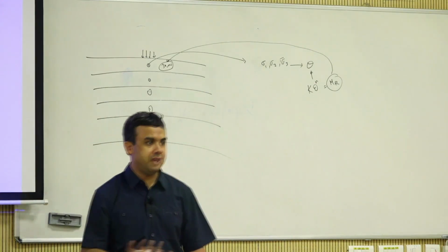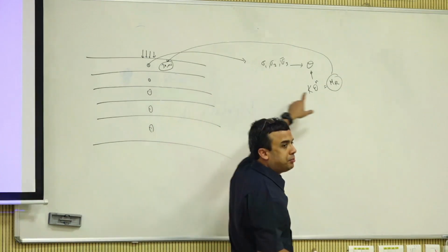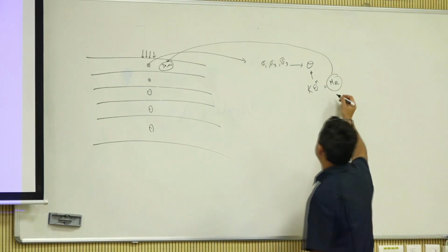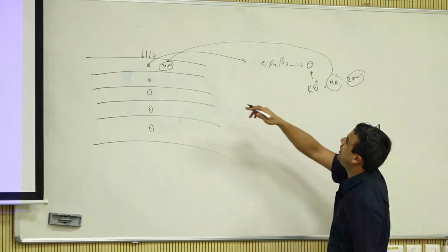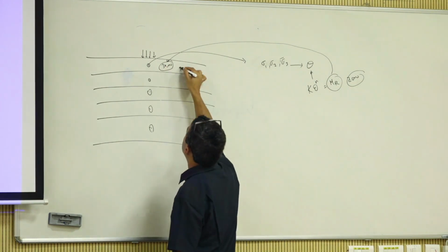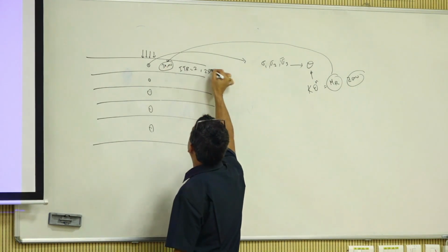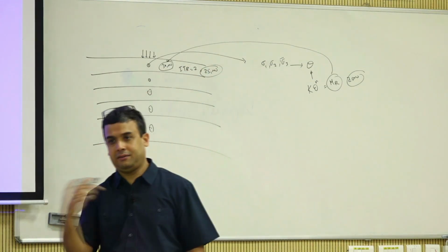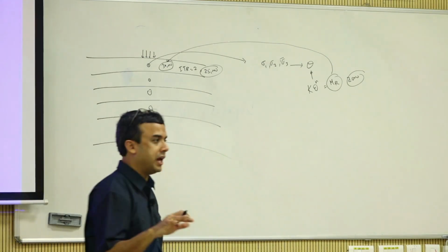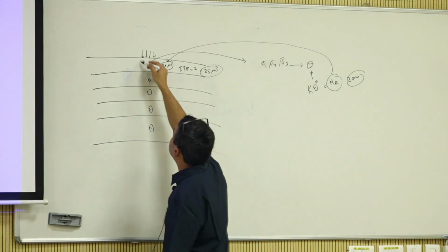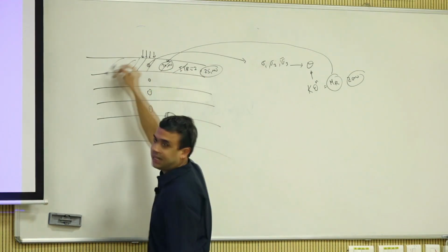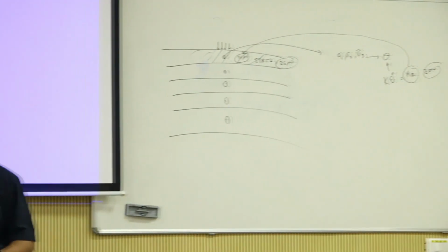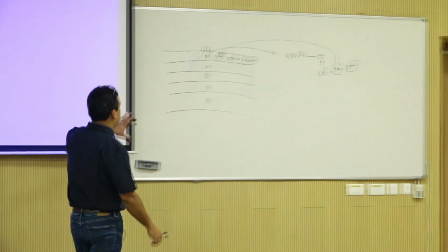Then compare this MR to this 30,000 that you assumed. Are you close? If you are not, take an average of these two numbers, rerun the analysis. Let's just say this is 20,000. So the average of 20 and 30 is 25. So in your iteration number 2, make it 25,000. Run the whole analysis again. Then check. Once you are close enough, you're like, okay, this is my converged modulus. Now I am confident that for this layer, I can assign this modulus and still be okay. I'm good, no problem. This you can do for thick layers.